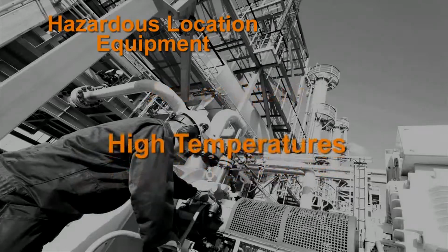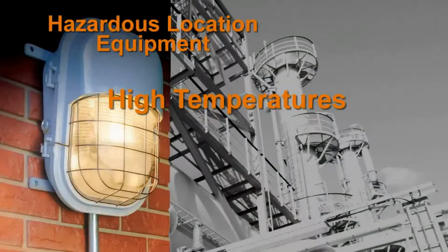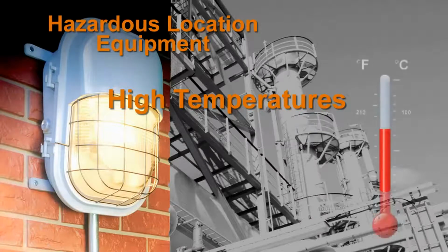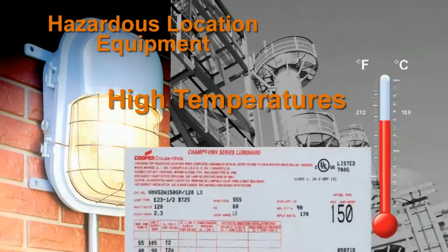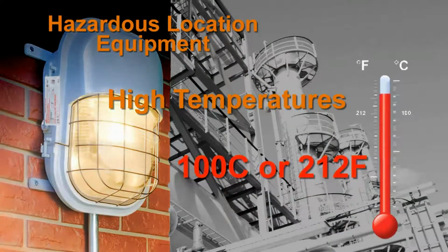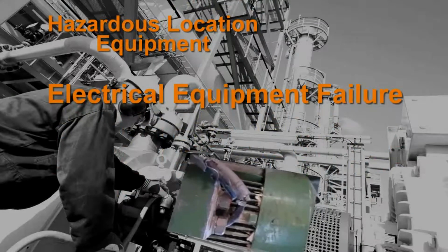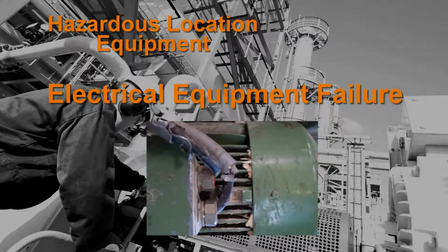The high temperatures of some heat-producing equipment, such as lamps and lighting fixtures, can ignite flammable atmospheres if they exceed the ignition temperature of the hazardous material. The National Electric Code requires special markings of heat-producing equipment with temperatures above 100 Celsius or 212 Fahrenheit. Electrical equipment failure is another way an explosion could be set off. A burnout of a lamp socket or shortening of a terminal could spark a real disaster in a hazardous location.